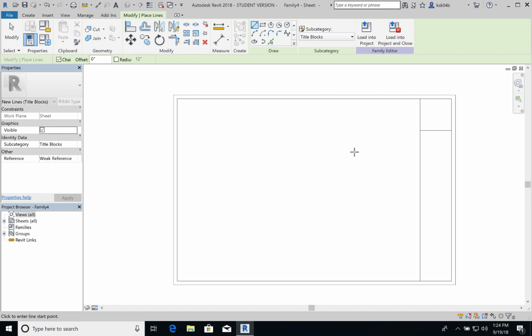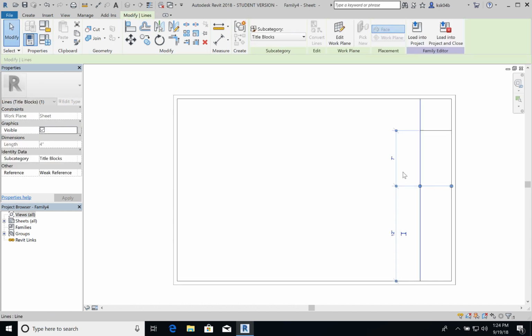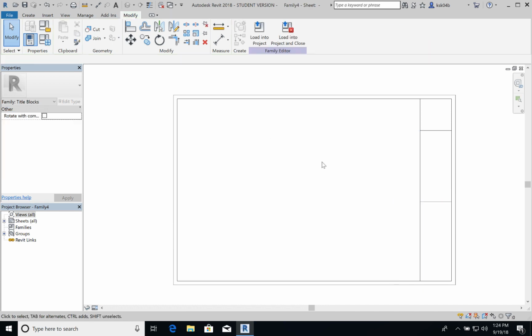The next thing I'm going to include is identifying project information. So on every set of sheets, you'll find the name of the project, the address of the project, anything specifically identifying to that project. So I'm going to leave a gap here that is about, let's say, 7 inches tall. This can be whatever size you want it to be. Some firms will make theirs actually more like 9 inches. So if that's what you want it to look like, then whatever proportion is fine with you.